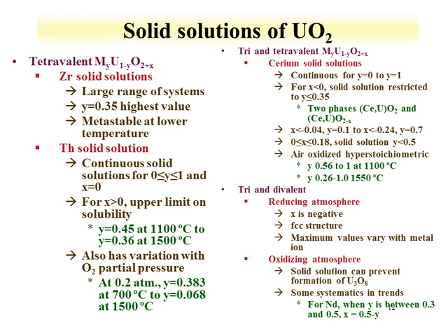Unlike zirconium, thorium has an ionic radius very similar to uranium, they're both about 1 angstrom, where zirconium is about 0.72 angstrom, so it's much smaller. Thorium makes a solid solution with uranium over the entire range.